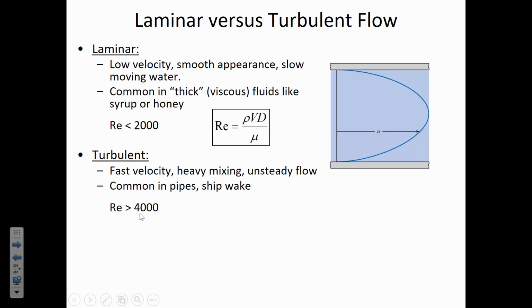So we'll see from our experimental standpoint what we think the dividing line between laminar and turbulent flow conditions is. So what would you get if you were between 2,000 and 4,000? Like what state would that be? It's called transition flow, and the way it works is, let's say you have a pipe, and the flow is moving very slowly through the pipe. So the slow-moving flow conditions would be laminar, but we're opening a valve downstream.